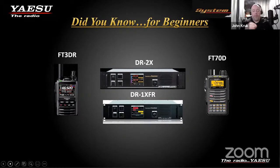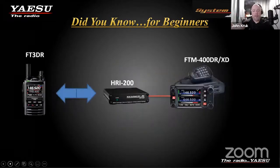In addition, where I kind of jumped ahead a little bit, it's also multi-mode, meaning it can be an FM repeater. It could be a digital only repeater, or it can be an AMS repeater where it's digital in, digital out, FM in, FM out, or, and we're one of the few that can actually do this, you can go in on a digital mode and be forced to come out on analog, or go in on analog and be forced to come out on digital. Or you can go in AMS mode, meaning analog or digital, and be forced out FM, or analog and digital and forced out digital. So that's the functionality, the versatility and flexibility of the repeater.